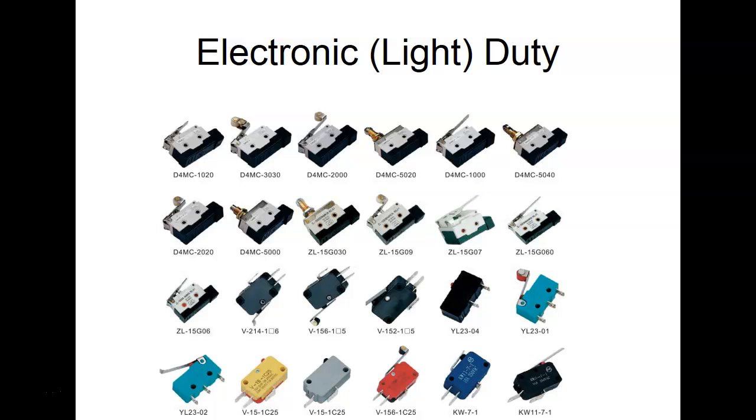Technically, these are proximity sensors, but we don't call them proximity sensors. We call them limit switches. They're used for all types of applications now besides just finding limits, right? Originally, that's what they were used for, like in mill machines, where the carriage would move, and when you hit a limit, it would automatically reverse.